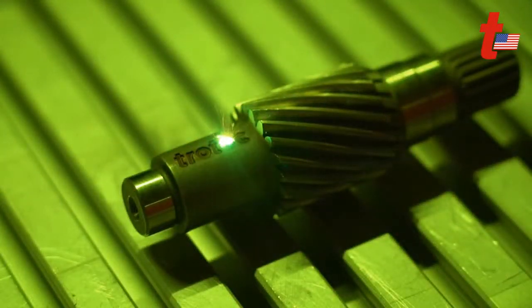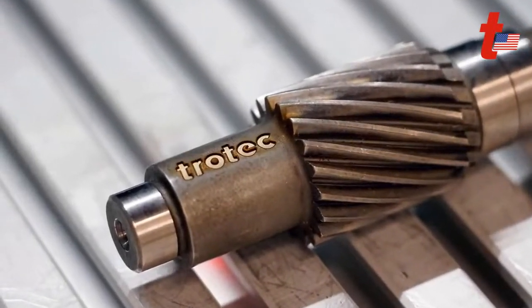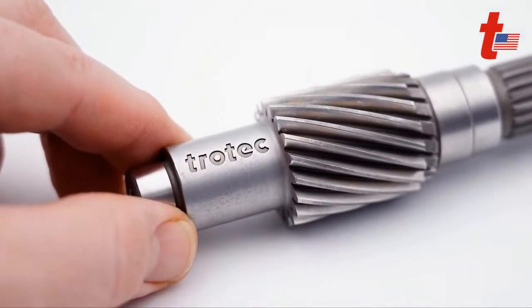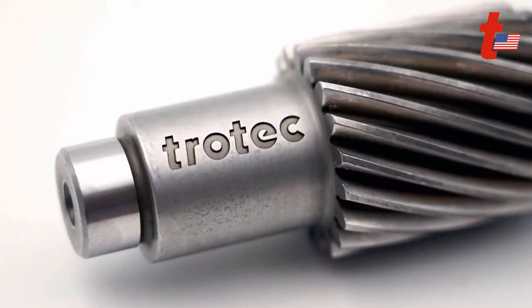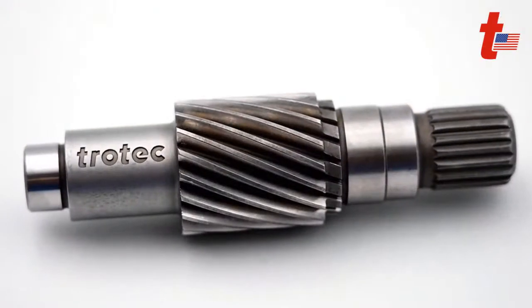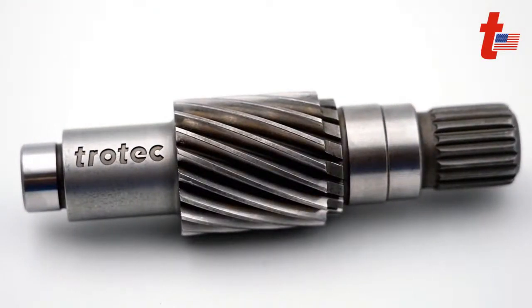And then as we go through after 20, this is probably 10, 20 minutes of engraving, we now have the finished result. And that is right out of the machine. I'll take a little Scotch-Brite pad to it. It cleans up nicely, and we now have that nice, beautiful, high contrast, really good amount of depth in the surface of the metal. This is probably a little more extreme than most people need. Most applications only require up to maybe 3, 4, 5/1000ths of an inch depth for certifications. This one is pushing closer to 15 to 20/1000ths of an inch depth, just more for visual appeal.